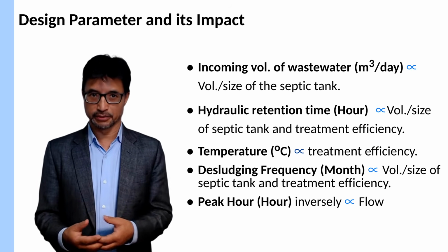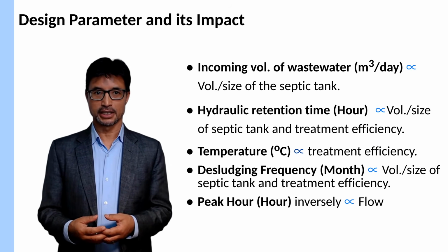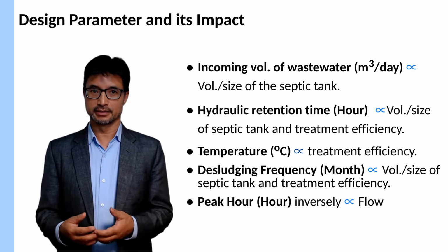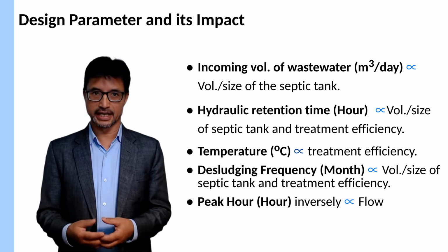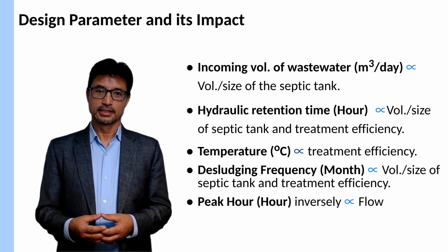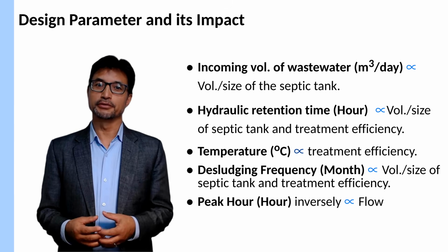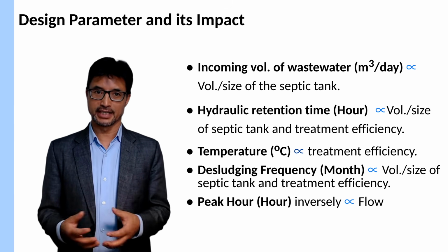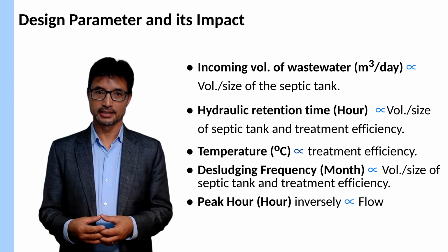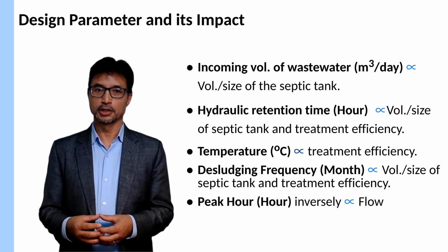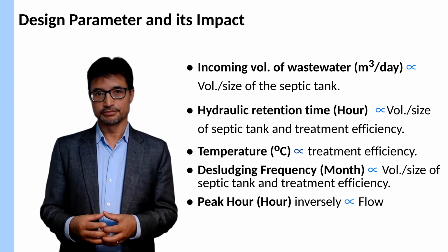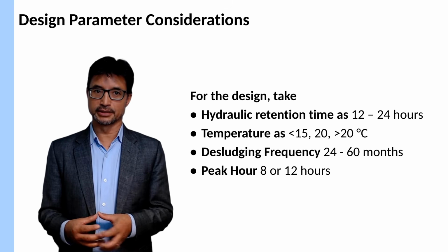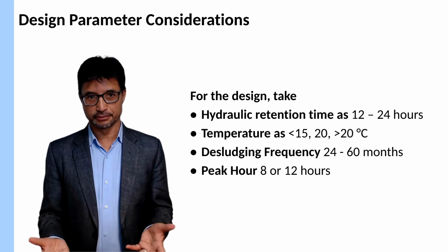Several factors determine the size of a septic tank. More incoming wastewater means a larger tank. Hydraulic retention time affects both tank volume and treatment efficiency. Similarly, temperature influences treatment performance, while the dislodging interval affects the space required for accumulated solids. Peak flow duration also influences the design flow. For practical design, we therefore need to select appropriate values for these parameters.